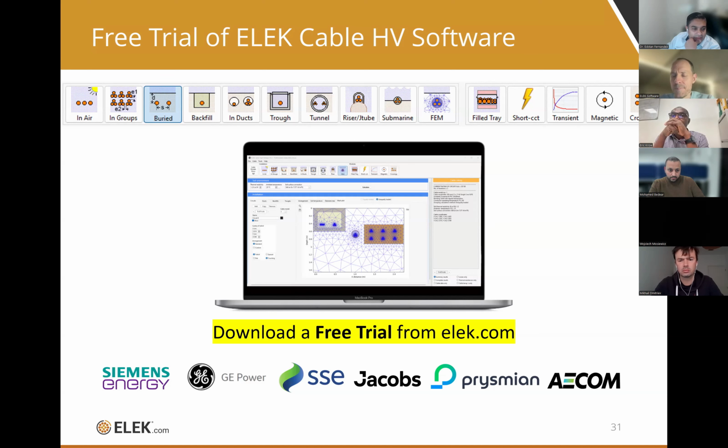The other question is, I think, the impact of marine growth. I think you touched on that in your presentation. Could we add any assumptions to it? You could possibly, in the cable model, add an additional insulating layer and give it some thermal resistivity. That's a possibility if you really wanted to do it. I've not heard of it being done.